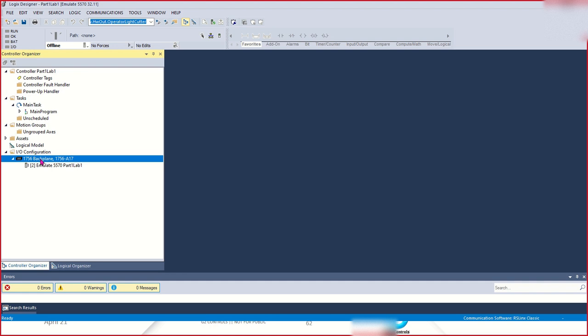In the emulator, we have limited IO configuration, because in the emulator only digital input and digital output we can configure. But the emulator can calculate all your program. It processes the whole program, but we are not able to configure the hardware input and output here.